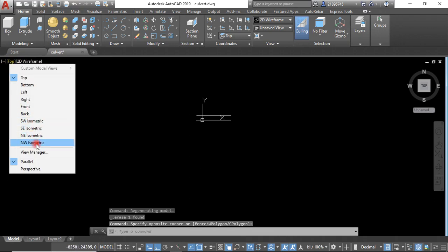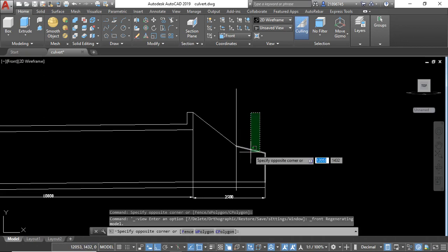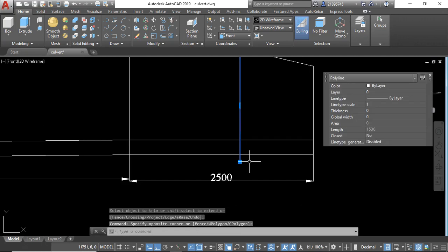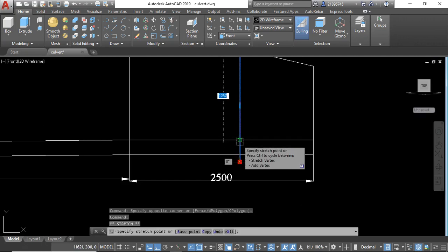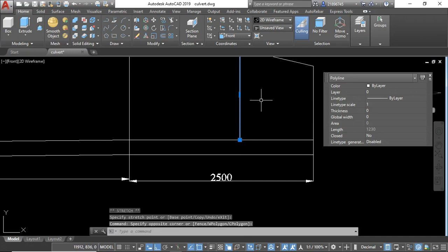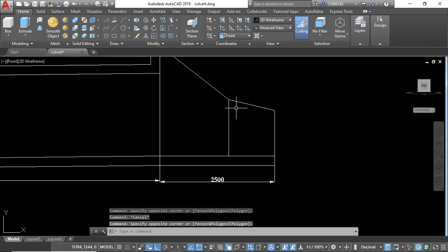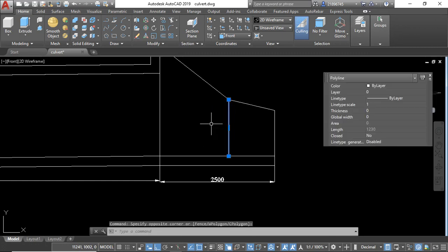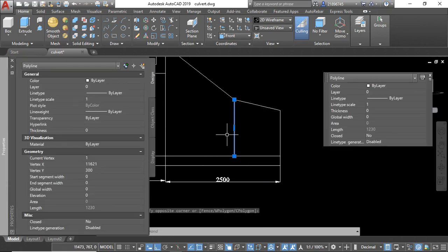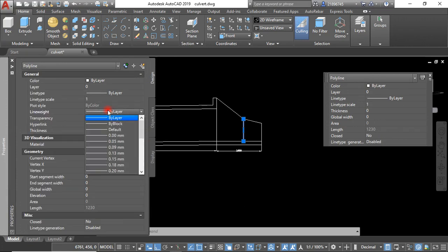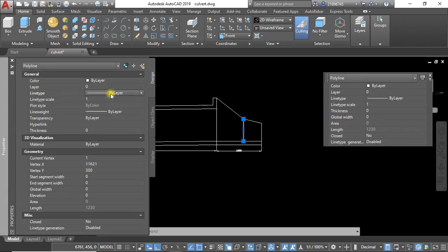Actually I have done most of the work here. So this one I can just come here and remove it, but remember, is it a solid line? Yes, it's a solid line, although maybe you need to change the line width, or supposing we want to have this as a dashed one, you can just click here and go right, type more. So now you have the properties. So you want to have a different line type, but you don't have.